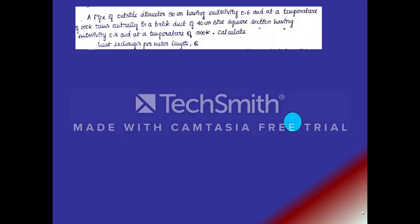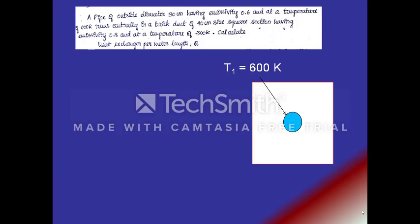There is a pipe having a diameter of 30 centimeters, emissivity epsilon 1 as 0.6 and at a temperature of 600 Kelvin. It is running centrally inside a square duct made of brick whose temperature is 300 Kelvin and whose side is a equal to 40 centimeters. We have to calculate the heat transferred between the pipe and the brick surface.